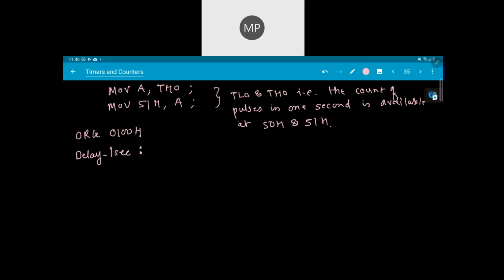And then how do we write? Simply MOV R0, #20. This is a decimal number, keep this in mind. Count to repeat 50 millisecond delay 20 times. Okay, keep the habit of writing comments, right?